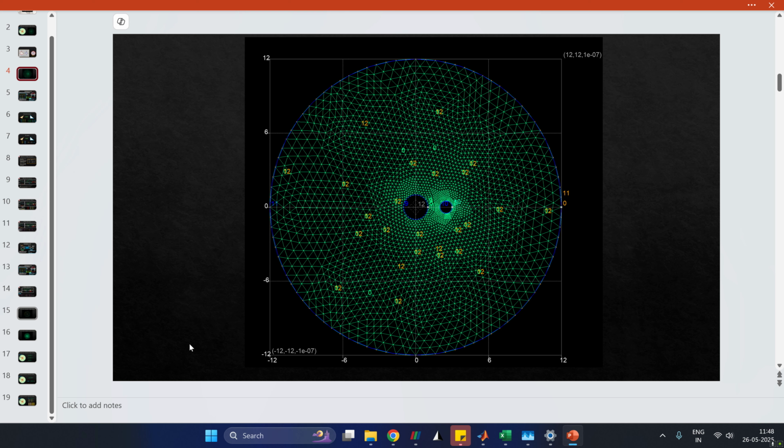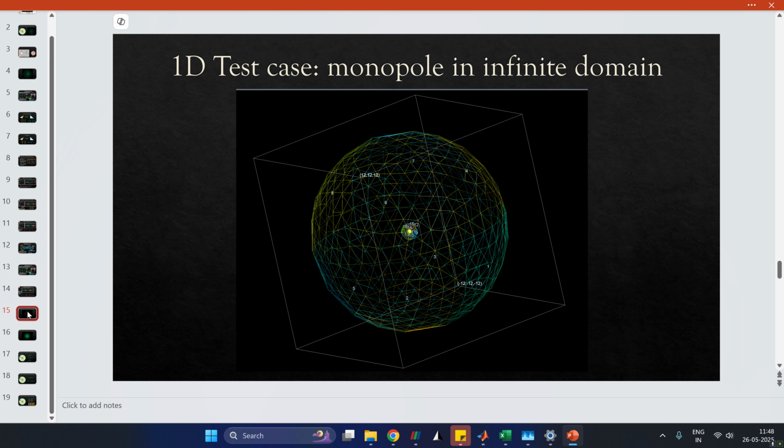So now instead of line elements, we'll just have triangular elements. We'll only be considering tetrahedrons here. We'll not go for bricks. And in the actual demo, I'll only be showing linears. So these will simply be linear triangles. And so for our Robin boundary condition, which we want to evaluate, we'll have to take a boundary integral on a triangle.